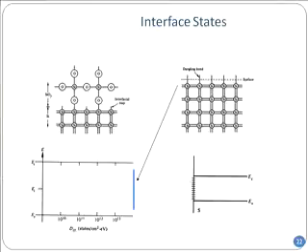So when you put the silicon dioxide, remember the tetrahedra I just showed you: silicon shared between 4 oxygen, and the oxygen being shared between 2 silicon. Remember the previous picture? That has been laid flat on the page, and that's how it looks. As soon as you bring oxygen, a bunch of those dangling bonds are satisfied because they take care of it. But the silicon dioxide has a different lattice constant than silicon. Therefore, not all of them are satisfied. You can see that the oxygen has taken care of some silicon, but a fraction of them are still dangling.